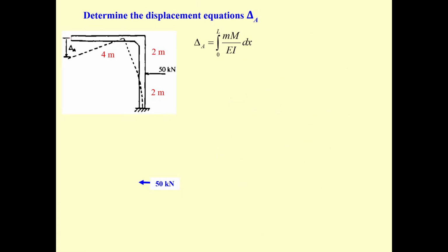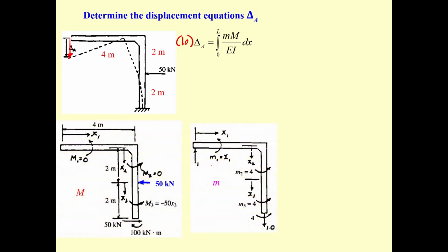And again, this is going to be our delta sub A. Based on this one, you've got to put 1.0 times delta sub A. So you've got to put the force. But in the solution, put the force opposite to your delta sub A. Again, the professor has an intention. This one will be useful later when you determine F sub A. But don't worry. If you put the virtual force opposite to your expected deflection, you're going to get a negative result.